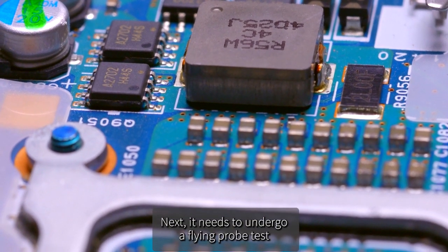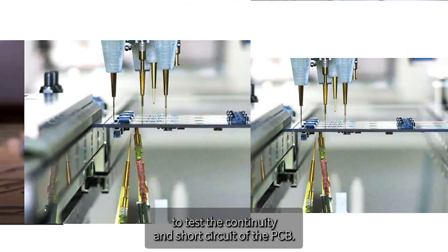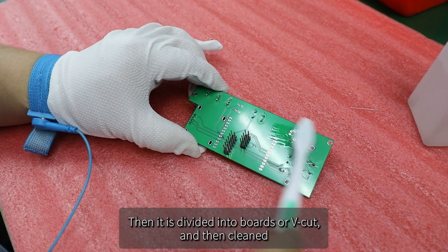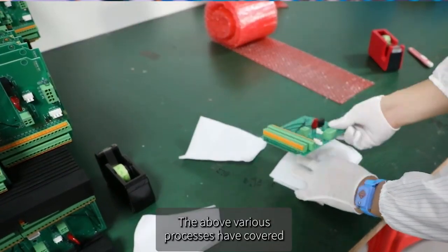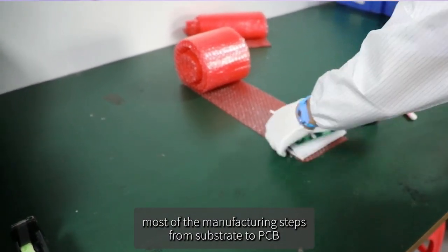Next, it needs to undergo a flying probe test to test the continuity and short circuit of the PCB. Then it is divided into boards or V-cut, and then cleaned again, and finally packaged and sent to the customer. The above various processes have covered most of the manufacturing steps from substrate to PCB.